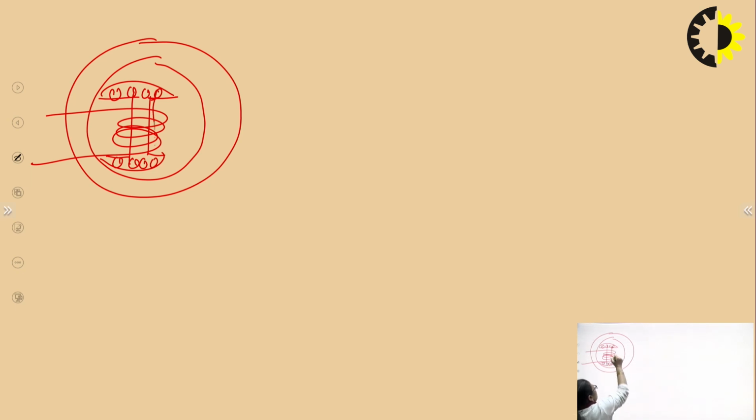They have copper bars inserted at the pole shoes, which makes it look exactly the same in construction as a squirrel cage rotor, right? The rotor windings give exactly the same replication of a three-phase induction motor with which kind of rotor? A squirrel cage rotor, right? And initially, we don't give the DC supply here. There's a switch being connected.